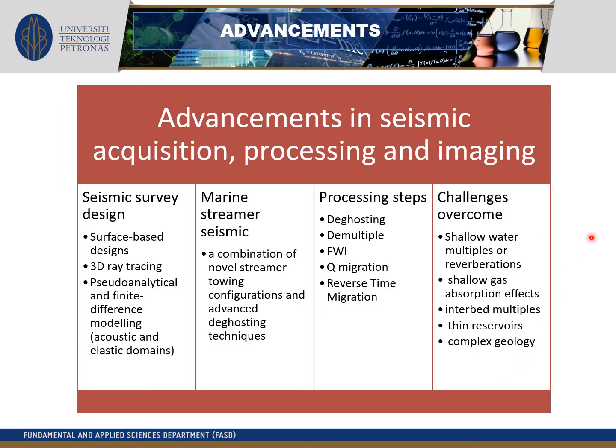And here are some additional advancements in seismic acquisition, processing, and imaging, also done by the study by Petronas. So there are 4 main advancements, which are seismic survey design, marine streamer seismic, some processing steps, and also some challenges that can be overcome currently and also in the future. So first of all, the seismic survey design is based on a few methods, for example, surface-based designs, 3D ray tracing, pseudo-analytical and finite difference modeling, acoustic and elastic domains.